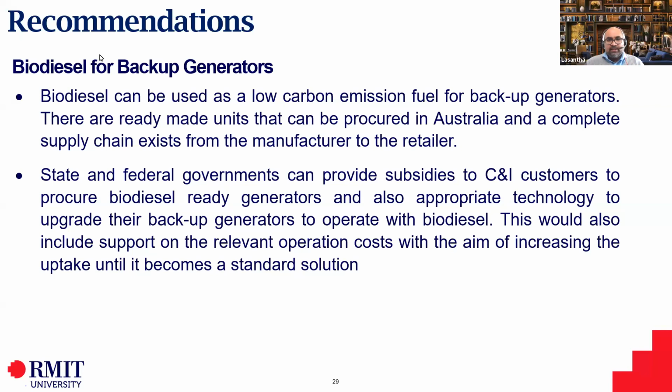But we haven't looked at the other reactive power compensation strategies in this project because it's out of scope, because our main sole focus was how to optimally utilize the backup generators in the demand response program. So we looked at the strategies that we can implement around the backup generators only. We haven't looked at the StatComs or the capacitor banks or any other inverter-based strategies here. It's just focused on the CNI customer backup generator and its functionality, what it can offer to the network.